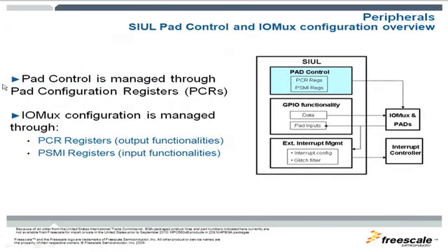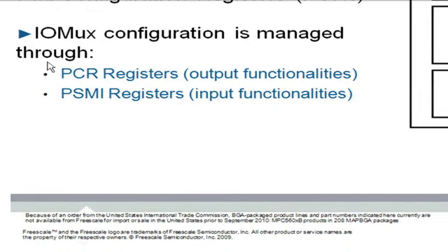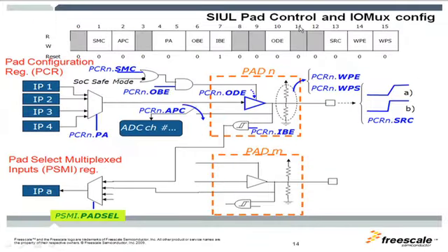Every pad has a pad configuration register for the outputs. And then for you to assign an input, you will also need to configure these other additional registers, the pad select multiplex inputs, or PSMI registers. So let's take a look at them.